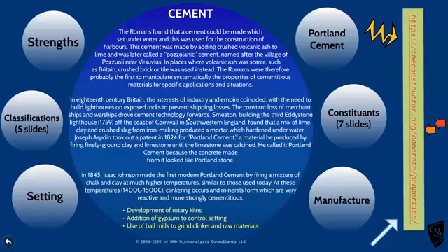Okay, and that wasn't a bad cement, used in lots of lighthouses and things, but in 1845, the real man of the story here, Isaac Johnson, made the first of what we would consider to be a modern Portland cement. He fired a mixture of chalk and clay at a much higher temperature than the others did. Almost identical to what we do today, he went up to 1400 to 1500 degrees centigrade. Clinkering occurs, and minerals form, which I won't go into, we're not doing a science class, which are reactive and more cementitious. They stick things together better.